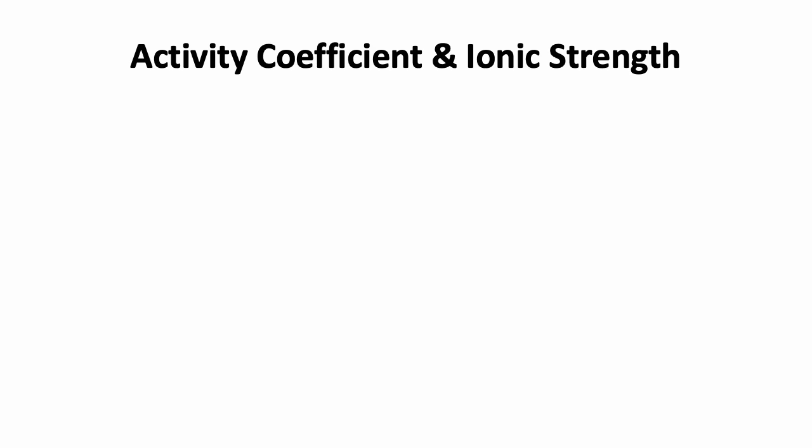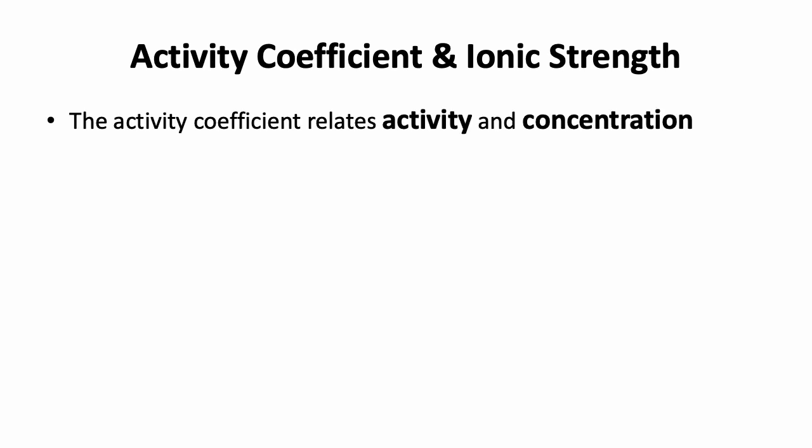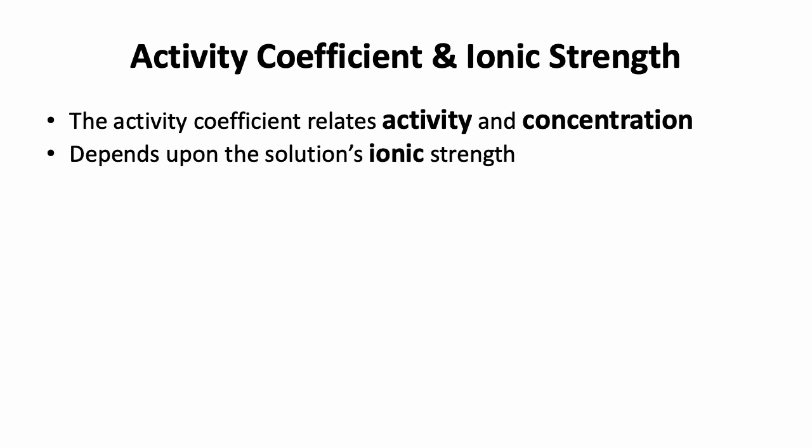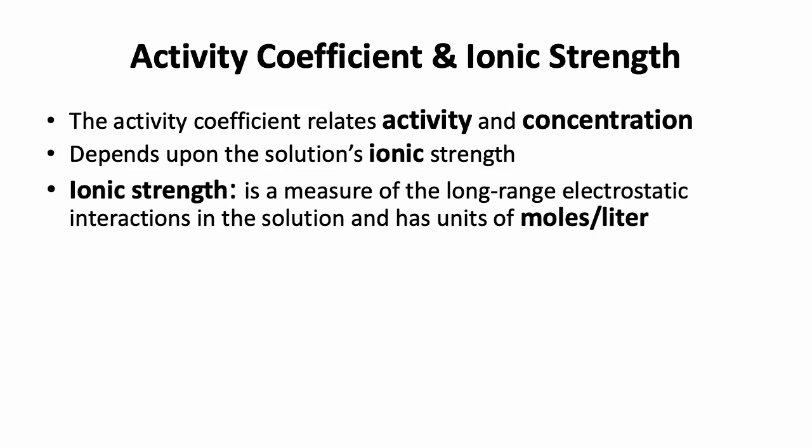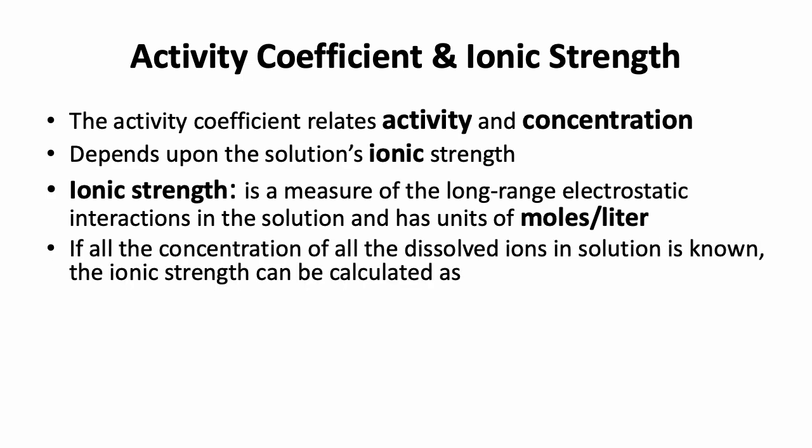We're also going to relate a term called the activity coefficient to account for the effects of all those ions in solution. Previously, we measured those ions in solution with the ionic strength. So the activity coefficient relates the activity to the concentration of the compound. It depends largely upon the ionic strength of the solution, and the ionic strength is a measure of those interaction forces and can be measured or estimated from measuring the ions themselves, measuring the total dissolved solids concentration, or measuring the resistivity of the solution, how electrodes move through the solution, that is.